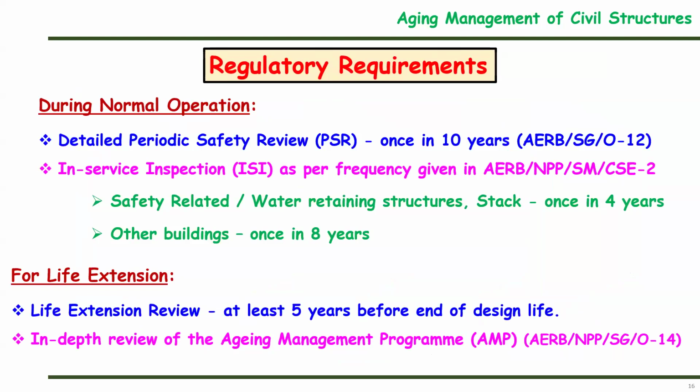Now, for our kind of structures in our department, there are some regulatory requirements. If my facility or structure is in normal operation, then we have to carry out a detailed periodic safety review once in 10 years. For safety related structures, water retaining structures or stacks, the in-service inspection has to be carried out once in 4 years, and for other buildings it is once in 8 years. Safety related structure means nuclear safety related structure where radiological hazard is involved.